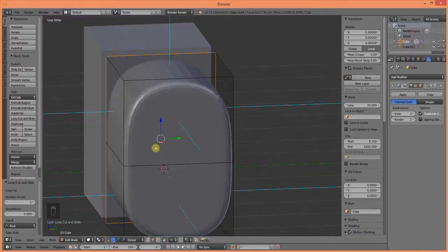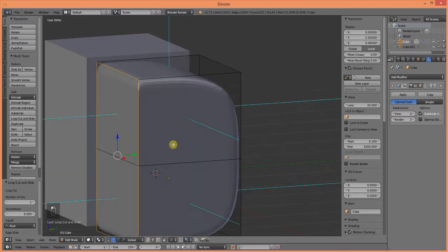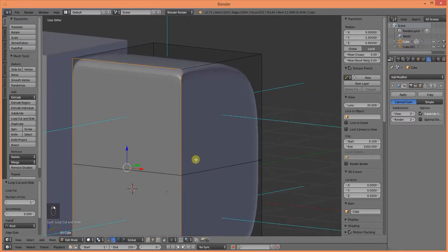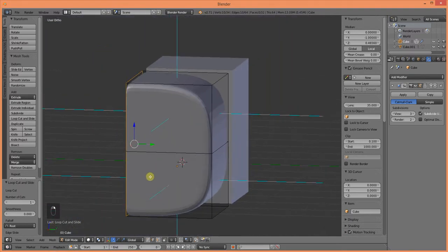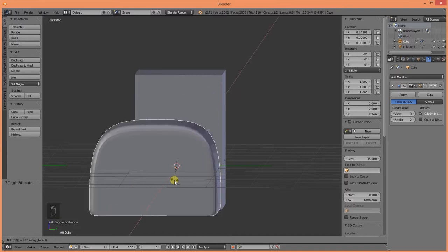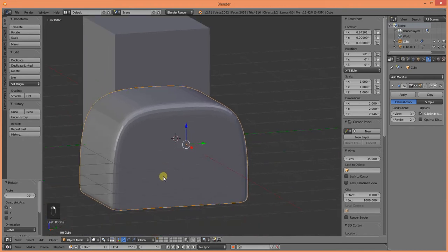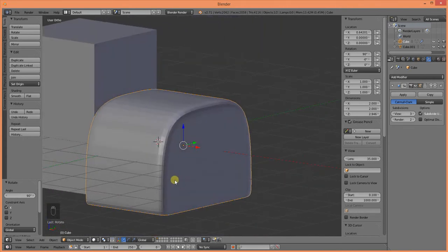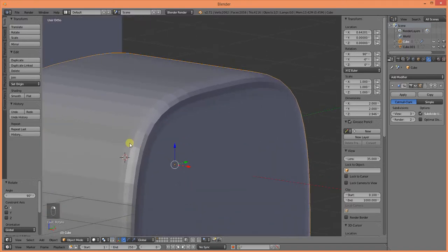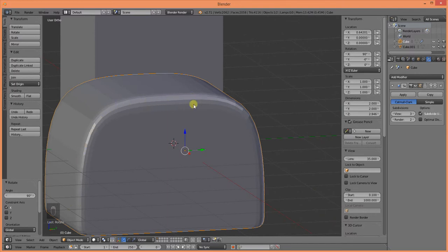If you notice, we still have that rounded pill shape up here, because we haven't applied another edge loop across that. So we're adding more and more detail to this. Now if I rotate this on the x-axis 90 degrees, I get myself a toaster. But I have the nice rounded edge over here and a nice arc up and across the top.